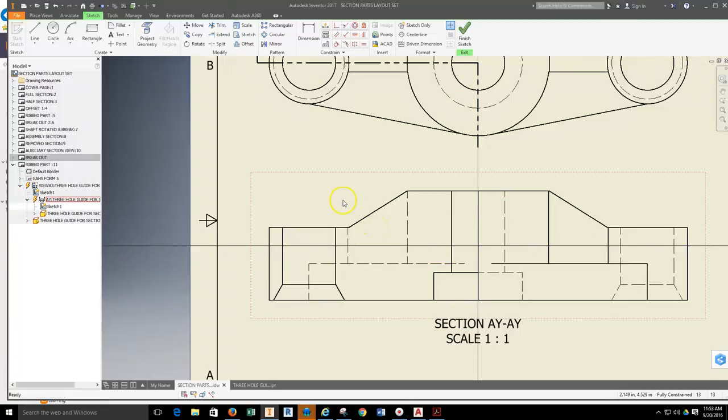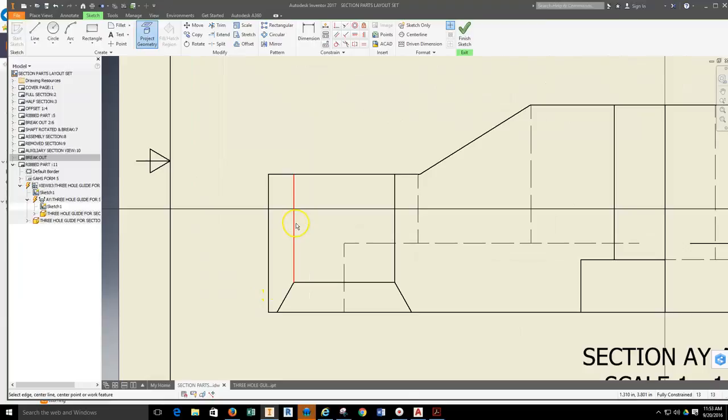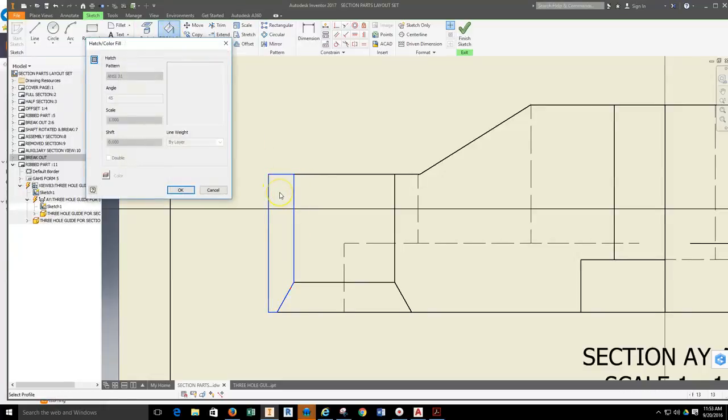And then just to show the basics of how to create a fill hatch region, I'm going to come over and use this tool here, Project Geometry, because for this particular section, I don't need to draw any closed loop. If I mouse up and then project the geometry for the profile of the area that needs to be sectioned, by doing that, I have a closed loop now, and I can grab Fill Hatch Region, come to the inside, and then select it.